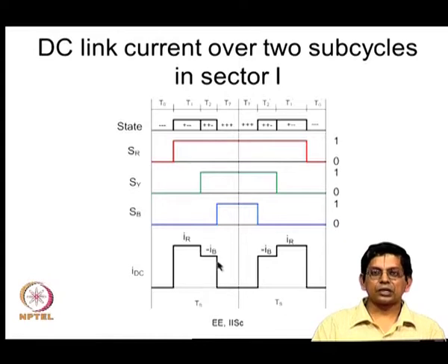The DC link current, if you look at the B phase current, now R phase current is positive. So, B phase is now, let us say, closer to the positive peak, then B phase would kind of be 120 degrees ahead of that. So, this is B phase actually negative. So, minus IB would be a positive quantity here. So, you have this current flowing through. When the second active state is applied, the amount of DC link current is different, but there is some DC link current.